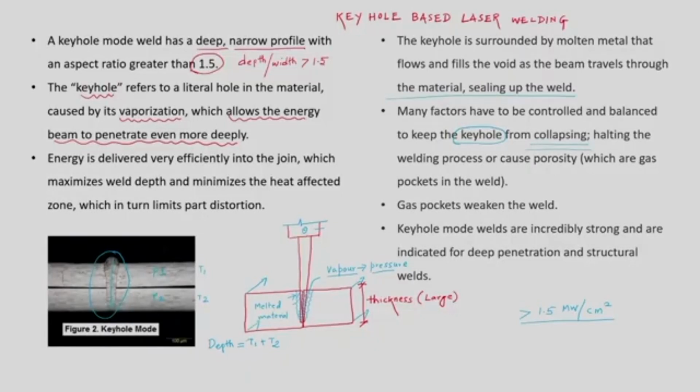and there has to be proper mixing of the molten material from both the parts to get uniform mixing, and it also has to be ensured that fewer pores are generated. The porosity of the material should be as low as possible, because of the bursting of the vapors during the operation. These vapors have very high temperature and high pressure.